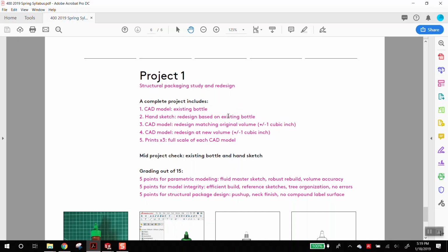I don't know if the whole method has a name, but the master sketch essentially is what you do: you create one SolidWorks sketch, just like we talked about, at the start of your tree, and you have all of your features refer to that sketch. As you recall, a feature consumes a sketch. Once you tell it to extrude, the sketch becomes part of the feature.